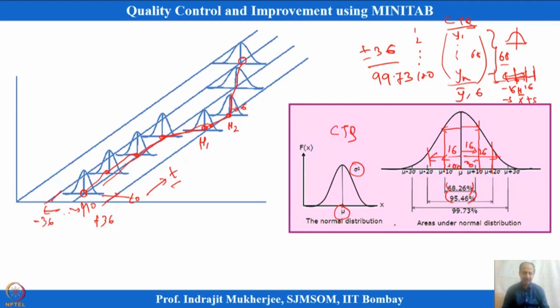In statistical process control also this concept is utilized, and we try to take more samples at a given time point, so that I can take an average. That is also important because individual observations sometimes follow different types of distribution, but when you take the average, they may follow a normal distribution. That is the assumption of a theorem known as the central limit theorem. So, that is why people prefer to use the average over here.